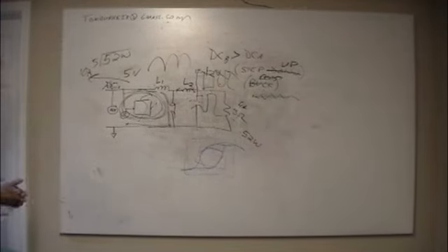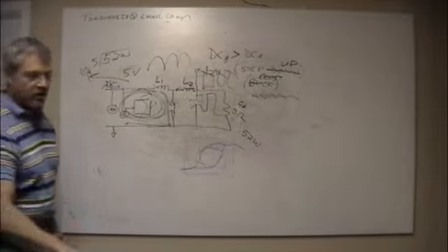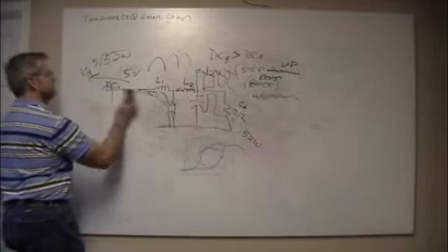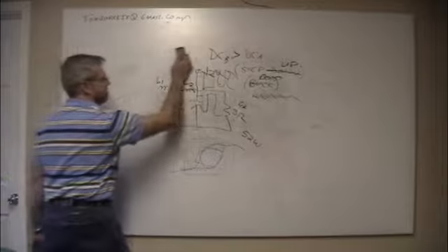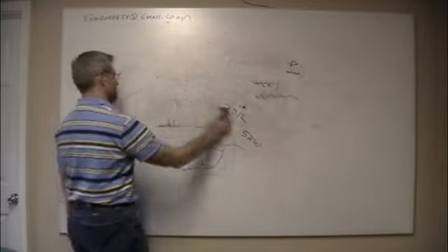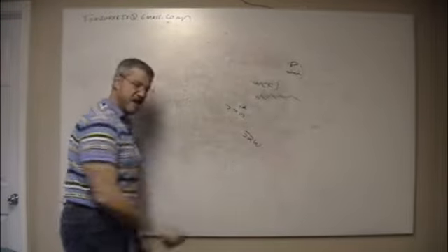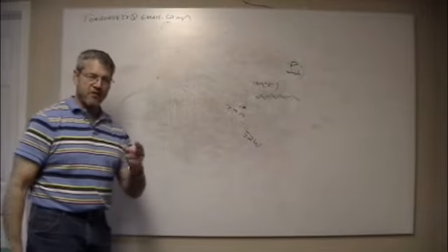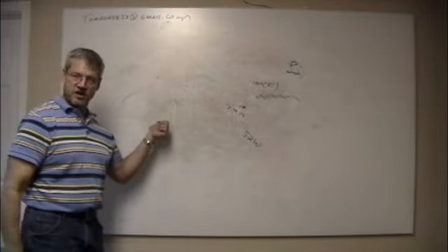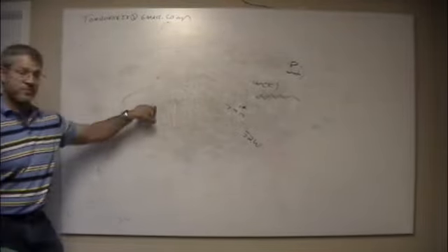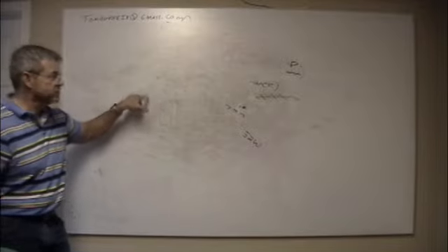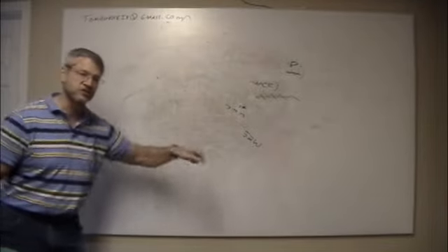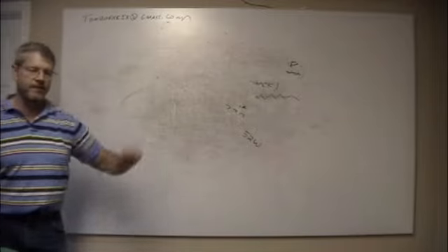Right. And now you start looking at power supplies that you're buying for your PC. These smart switching power supplies, 800 watts with PFC, power factor correction. It's electronic power factor correction because you're putting all these electronic things in, and the switching all looks inductive because you're hitting inductors and powering things on and off hard.